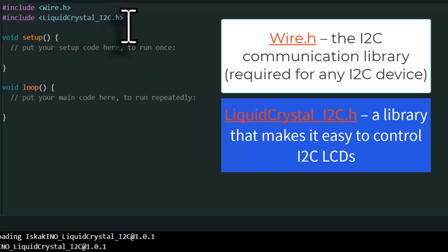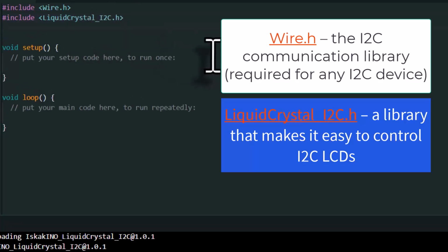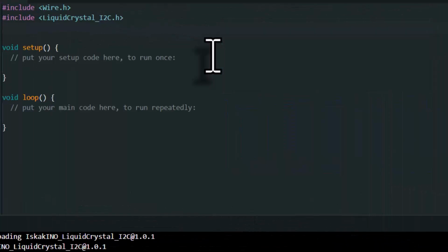In the next line, if you remember, in the radar lessons we had a servo, and when we imported the servo library, we had to create a servo object in order to use it in our main loops and functions later in the program. We do exactly the same thing with our LCD. We have to create an LCD object, and I'm going to call it lcd.